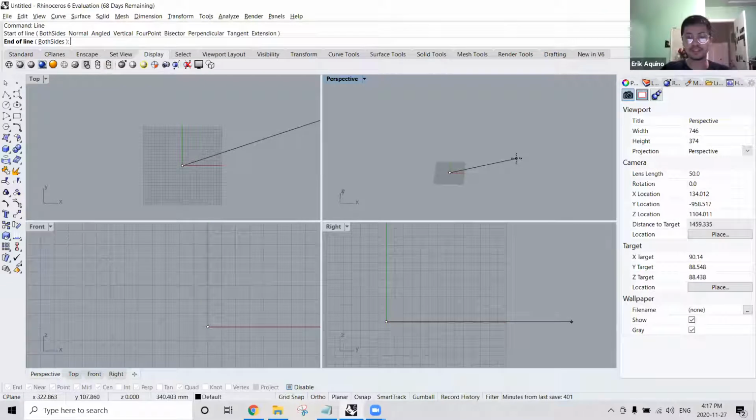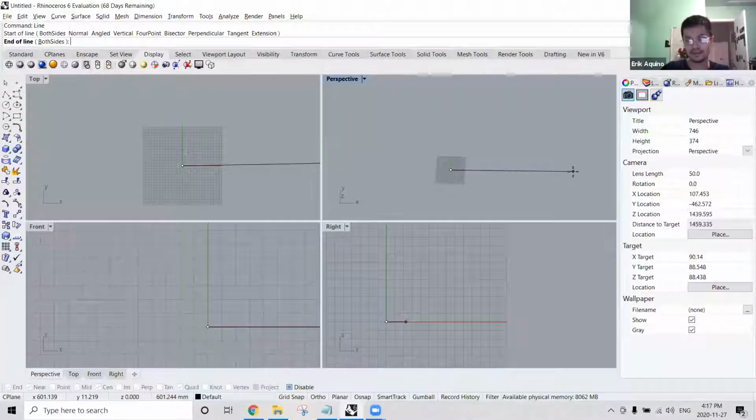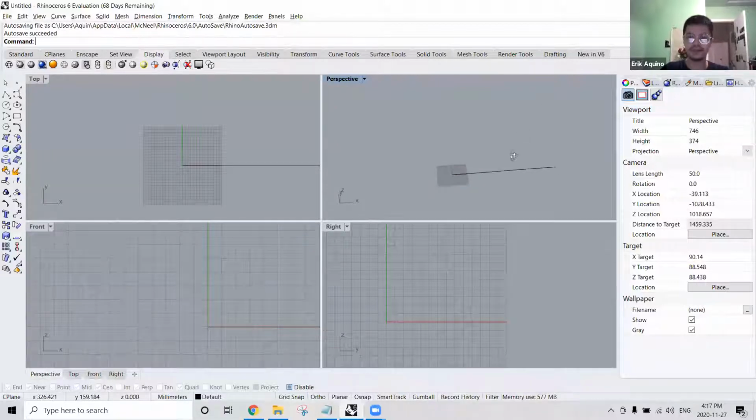So I can insert another coordinate. I will make a point somewhere on our x-axis, so I will type in maybe 500, comma, we're not gonna have this in the y-axis, so this will be 0. You can see that's already sort of locked, and you could specify even further saying that our z-axis will also be 0. So once I click, there, I've got my line.